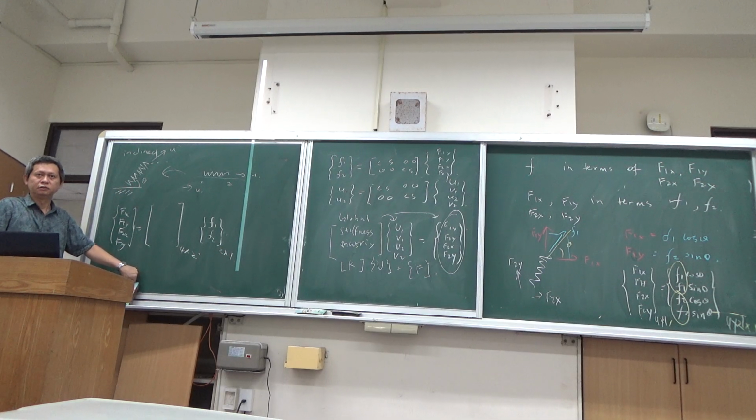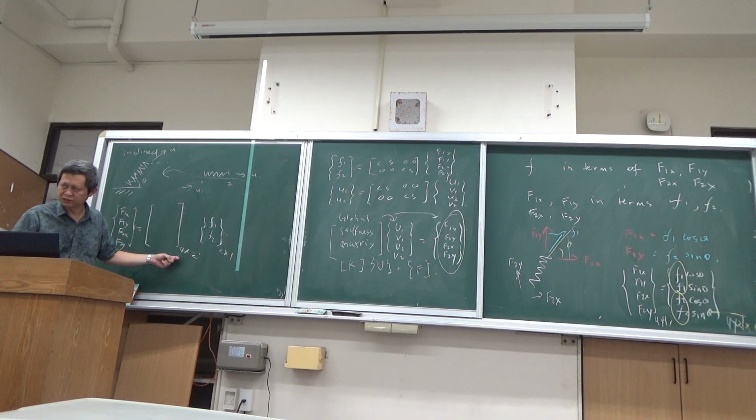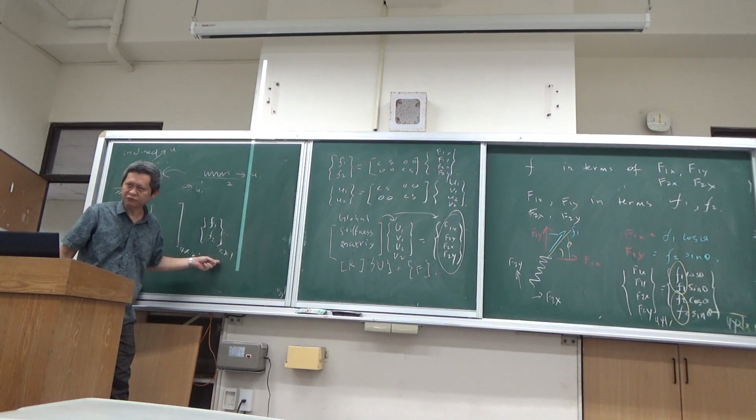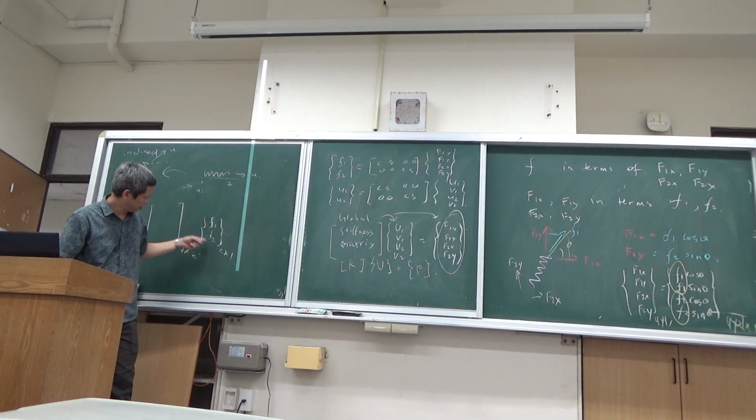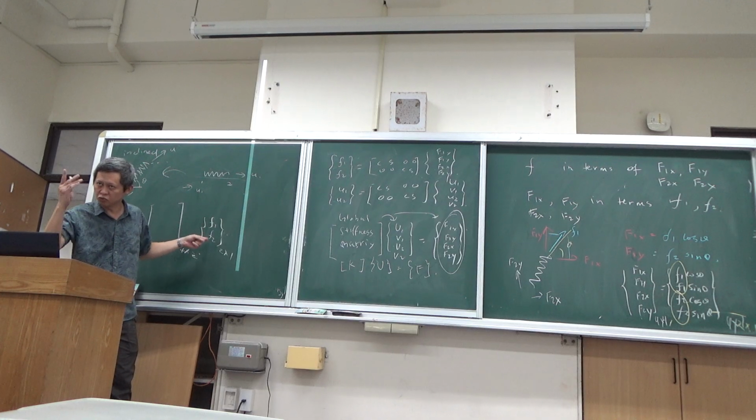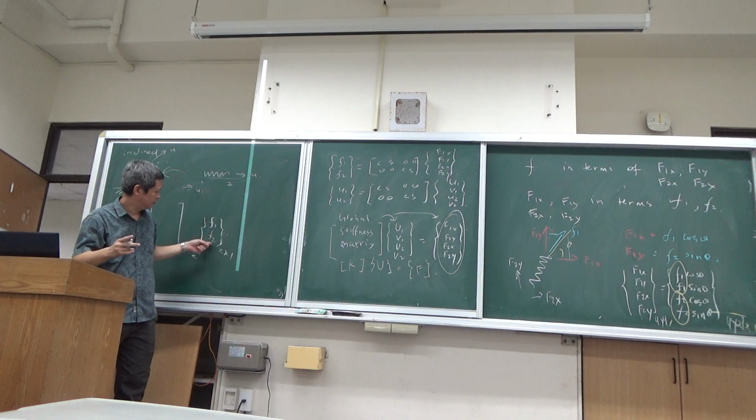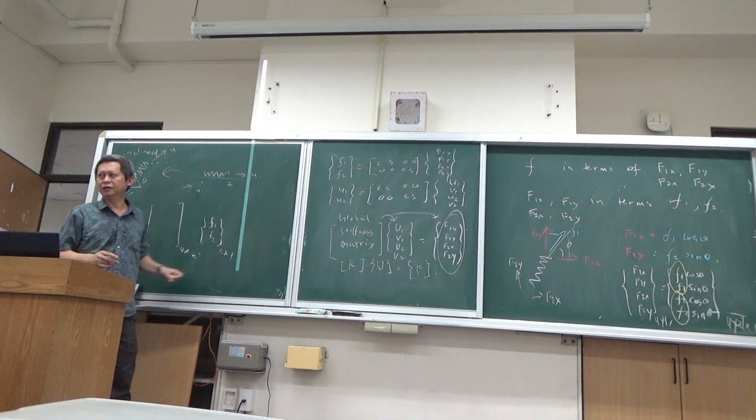Okay? So this transformation you must take note of, as we tell you what is finite element structural analysis by matrix. Okay? So you must be able to re-express this force vector into a matrix of the right size, then do the transformation times the unknown variable. Your unknown variable has 2 forces. Okay? Then it's going to be 2 by 1.